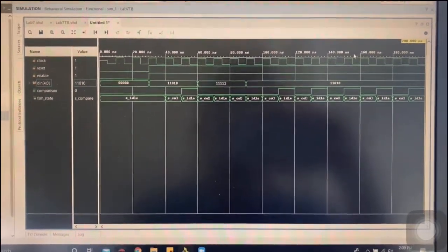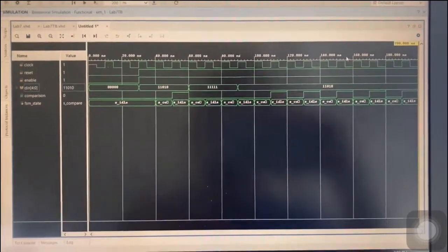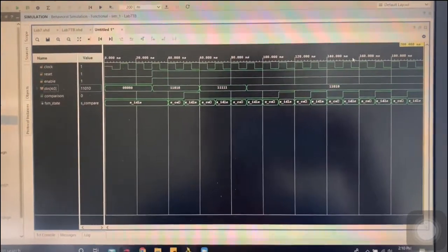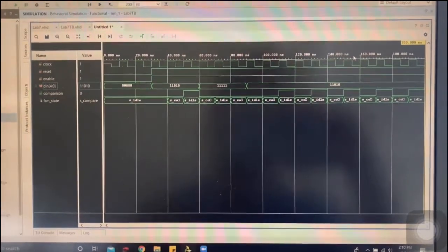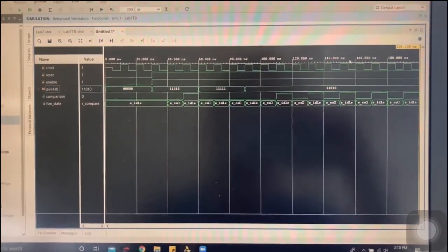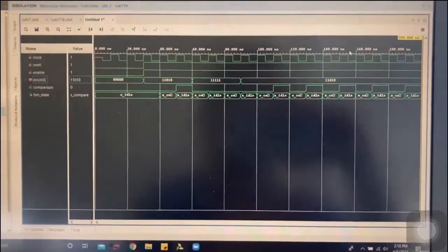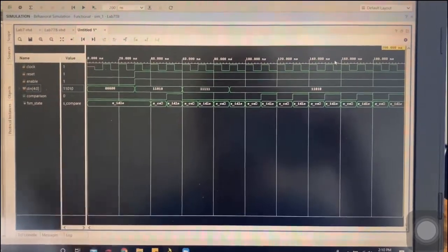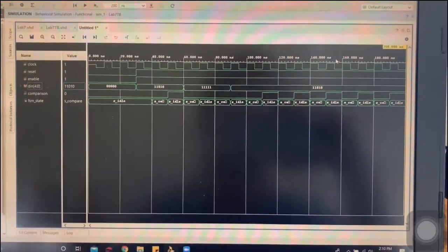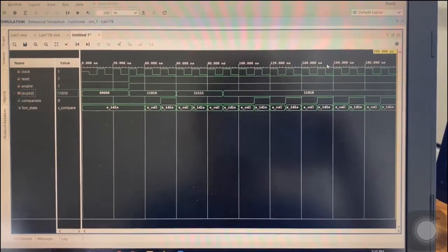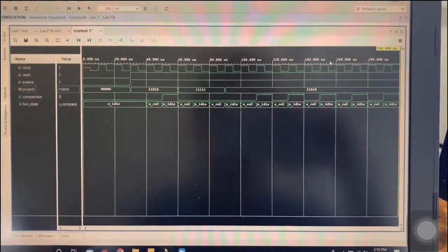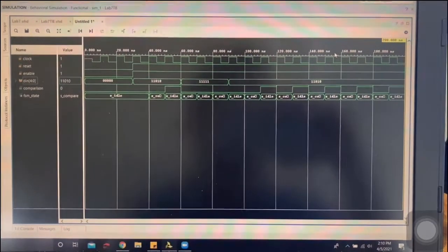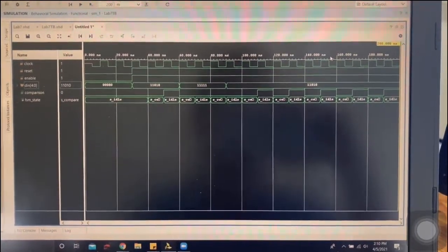So since my final project for embedded systems is an FPGA project, I have to actually show this working on the board. I've got to make a couple of edits real quick to get this to the board in a way that I can use it, because I don't have an infinite number of slide switches on my board. So I'm going to adjust this FPGA module a little bit so that it takes in just a 3-bit input instead of a 5-bit input. And then I will hop back into the video and show you what I did.